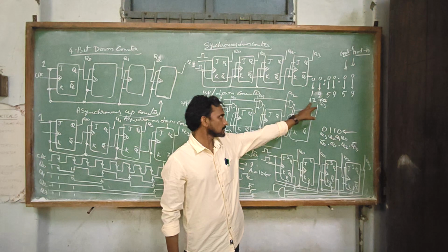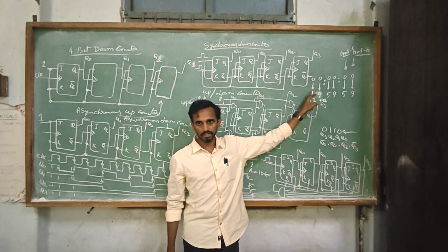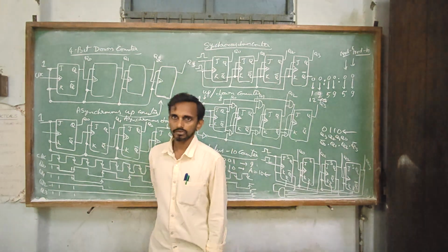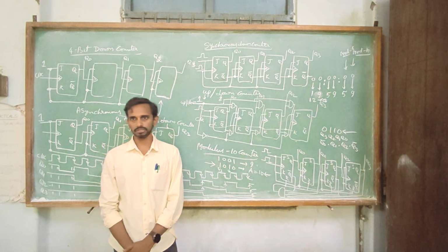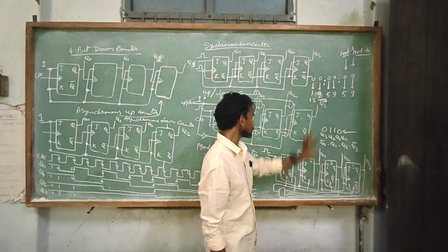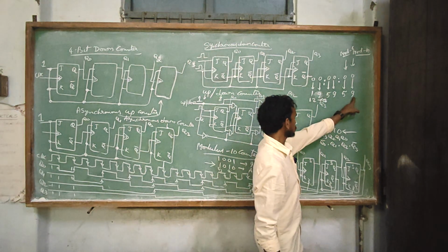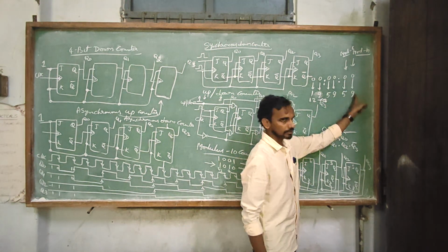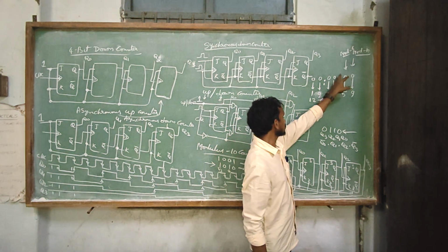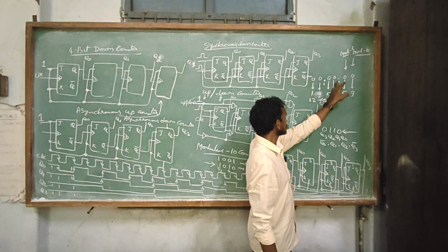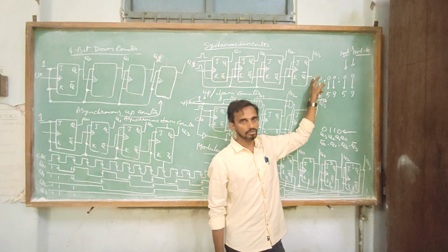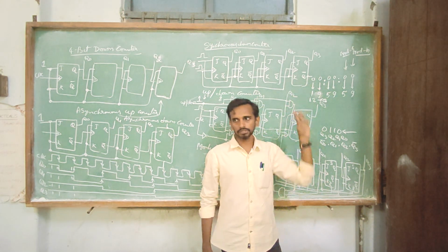When the second digit is 0, the counter has to go up to 9, and when the second digit is 1, it has to go up to 2. You may require an additional condition over there. So we have to configure both of them together. Here each counter is configured separately: 0 to 9 a decade counter, 0 to 5 another mod 6 counter, mod 10, mod 6, here mod 10, mod 2, but these both counters should be configured together.